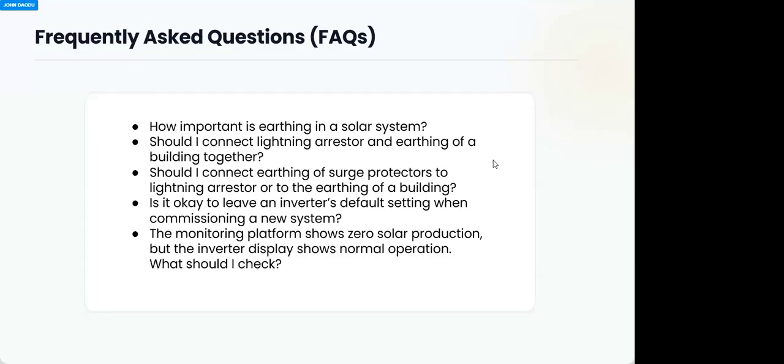So now the order of connection of these three components that you mentioned is the breaker, the AVR, which is the regulator, unless you are talking of AVS, which is automatic voltage switcher, which is part of the components. But let me even include that: AVR, AVS, circuit breaker, and surge protector. Now, your AVS, which is the automatic voltage switcher, is monitoring voltage up and down and overload in terms of current.